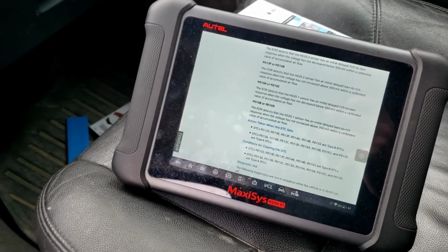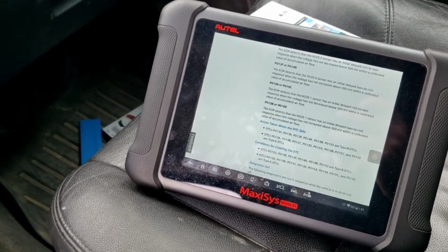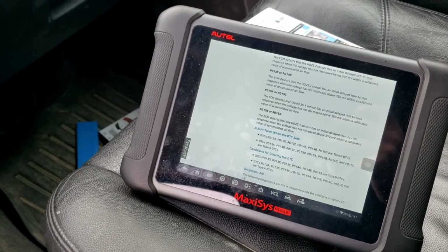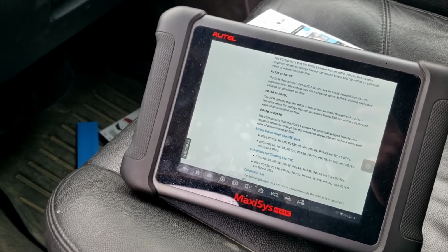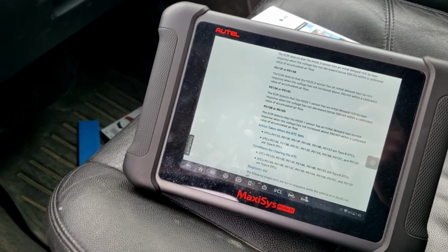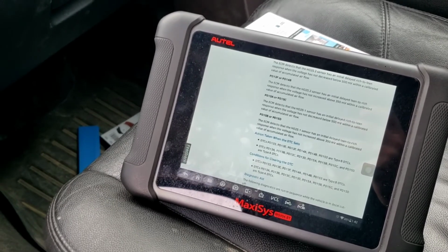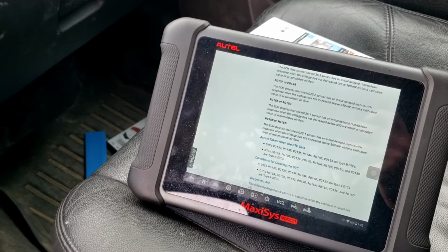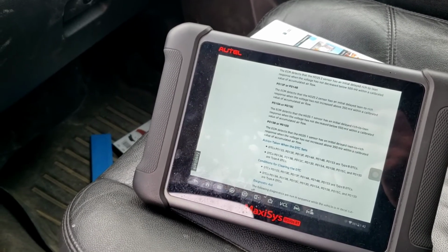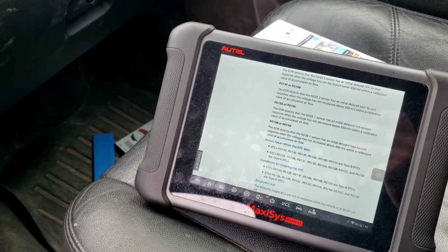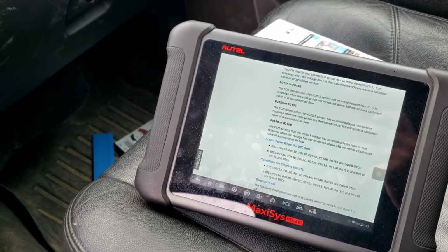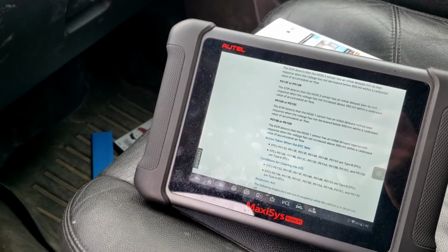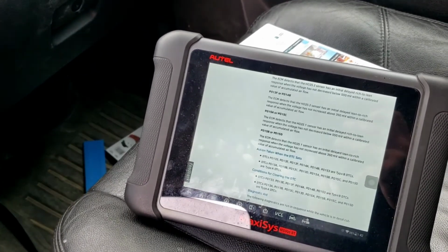But that is it for now for this vehicle. We're just going to have to go to the vent solenoid in the back, see if that's plugged up, check all that out, get it cleaned out, and then redo the test. May need a new part back there. As far as the O2 sensor goes, take it out and make sure there are no exhaust leaks or vacuum leaks or anything like that. But more likely it's just a slow response on the O2 sensor. And that'll be it for this vehicle.